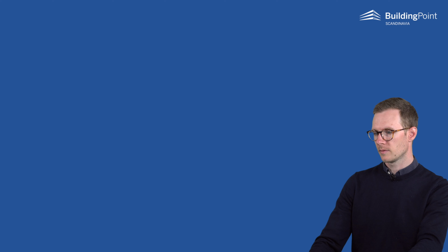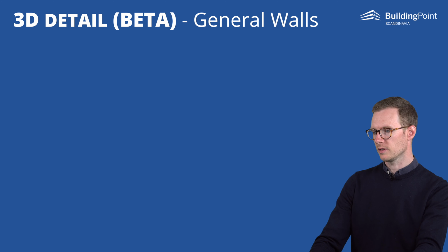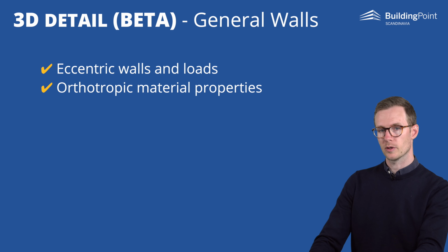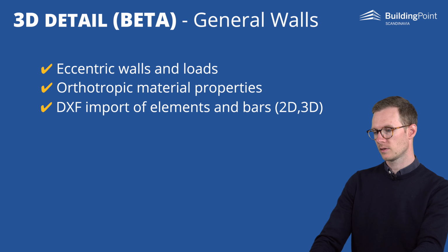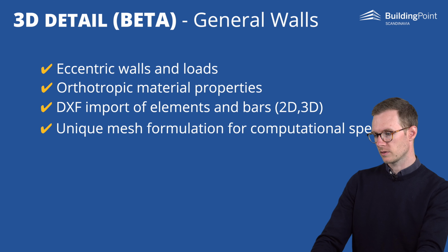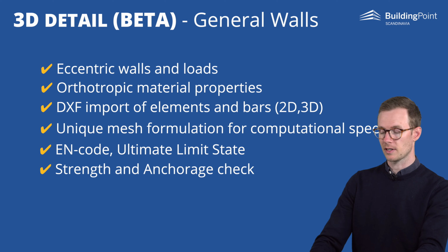Yeah, so let's look at walls. You can also do walls with eccentric loads and eccentric walls. You can see it in the picture here. I will also show a demonstration of it. You can have orthotropic material properties. You can also import with the DXF format, both elements and bars. And there has been implemented some unique mesh formulation for computational speed. And this is also limited to only ultimate limit state.